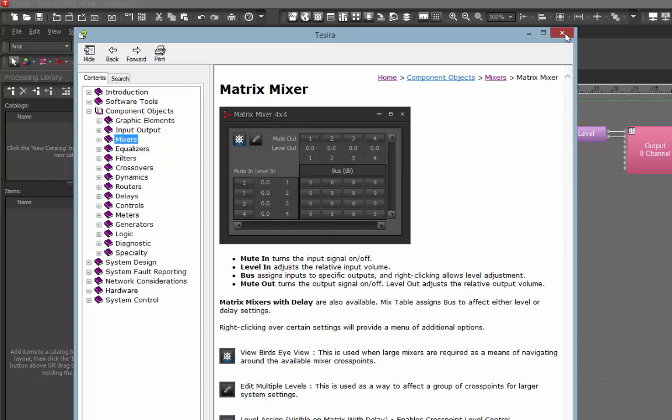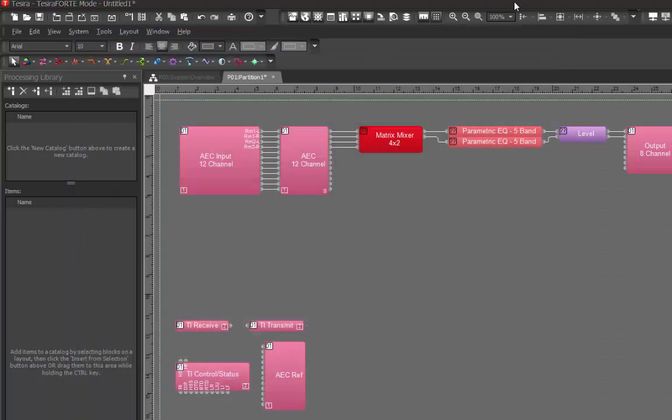The thing with Biamp versus other DSPs is you actually have to have a bit of knowledge of what you're trying to do, because you're kind of creating it from a blank canvas. So it's not a fixed architecture DSP like a Clear One or something, where everything's sort of predefined. This is like you've got a blank slate, drop in your inputs and outputs and make all the connections in between.